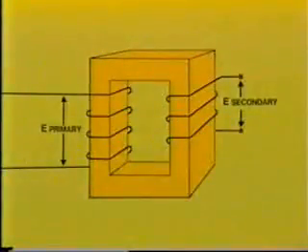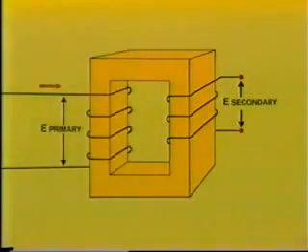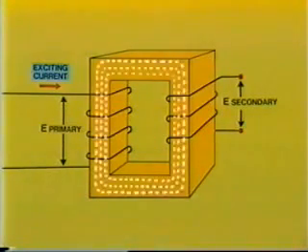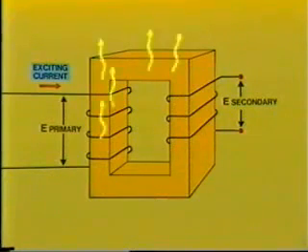The no-load losses are due to the current that flows when the transformer primary is energized, but with no load on the secondary. This no-load primary current is called exciting current. It is necessary to maintain the induced magnetic flux in the iron core. But it also gives rise to losses in the windings and the core. These no-load losses depend upon the transformer core material and its dimensions.